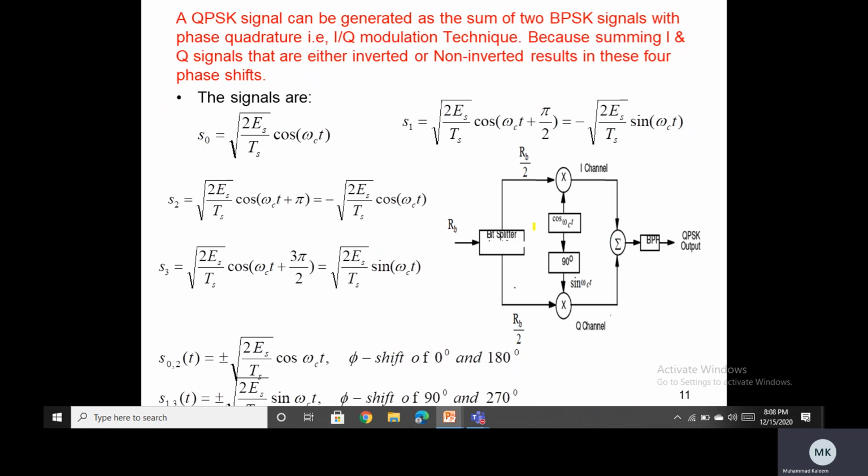On the transmitter side, RB is the bit stream coming in, input to the bit splitter. So a binary data stream is split into the in phase and quadrature phase components. These are then separately modulated onto two orthogonal basis functions. In this implementation, two sinusoidals are used.